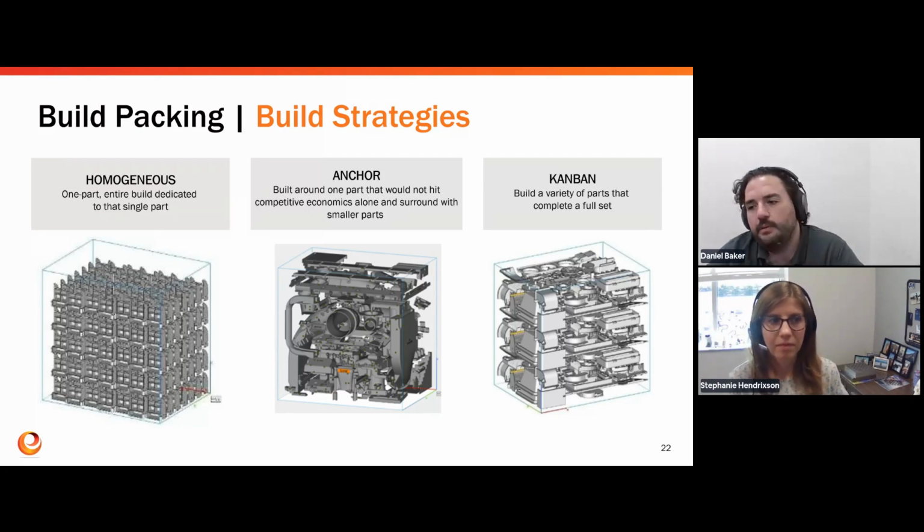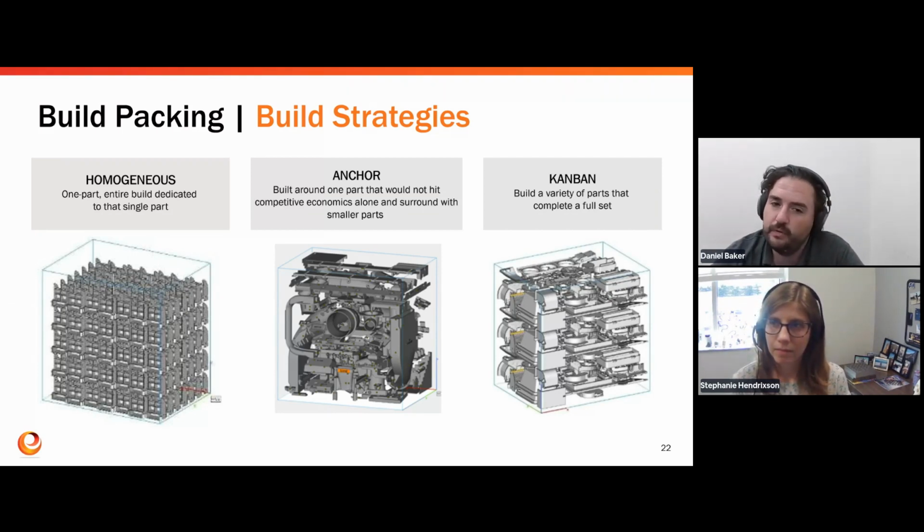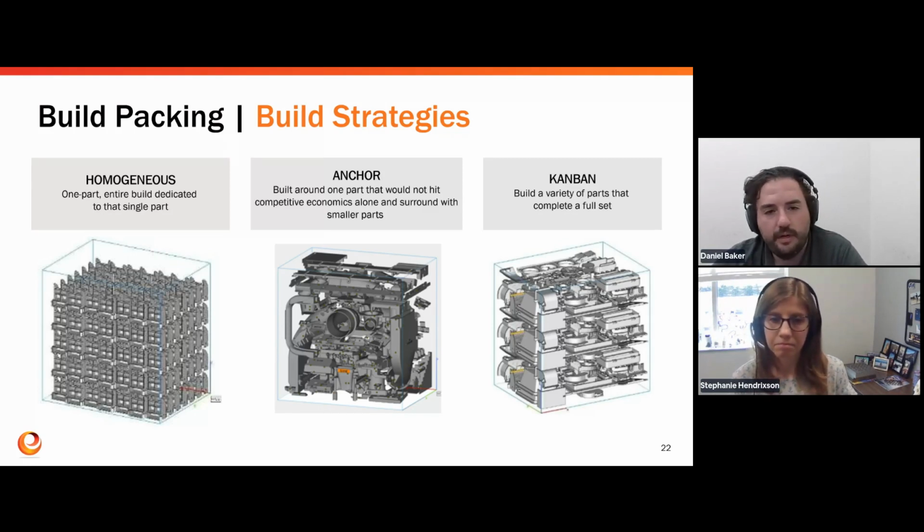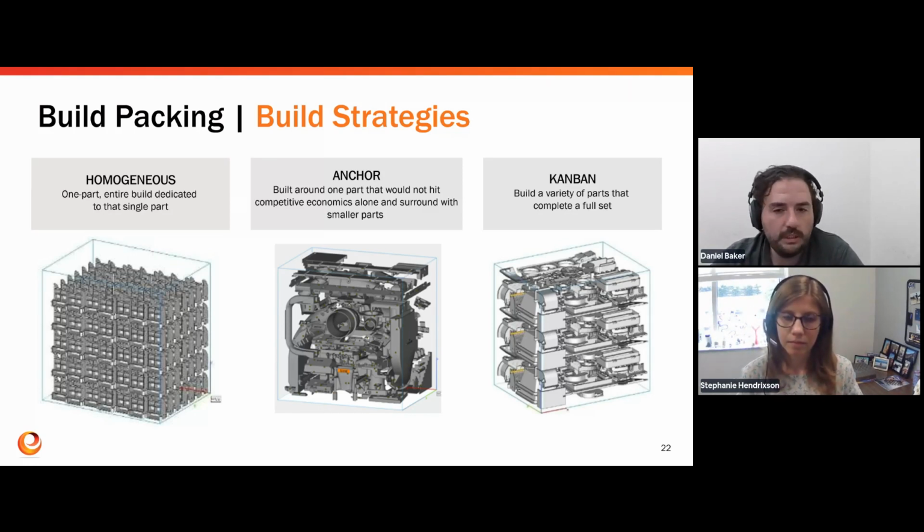I mentioned it at the beginning, but one of our services is 3D scanning and reverse engineering. We're just outside of Atlanta, and it's pretty heavily manufacturing focused out here. So we have a lot of legacy shops that don't have digital versions of their parts anymore. They just have old legacy parts that have been phased out of production, and then they need a few spares here or there that are critical for service or warranty for their end use customers. They will typically bring over either a machined part or a legacy part they had from molding, have us scan it, and turn it into digital CAD.